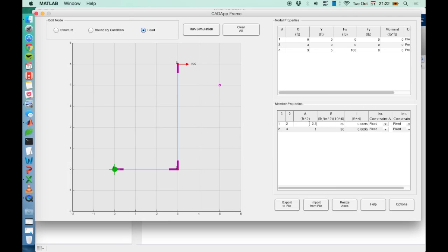These values have been calculated as A equals 2.3148 times 10 to the negative 5 feet squared, and I equals 3.4722 times 10 to the negative 6 feet to the fourth, based off of Ku equals 100,000 pounds and K theta equals 15,000 pounds feet squared provided in the example when E is 30 million psi.